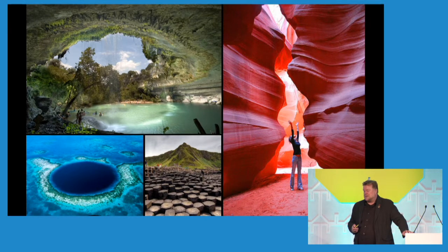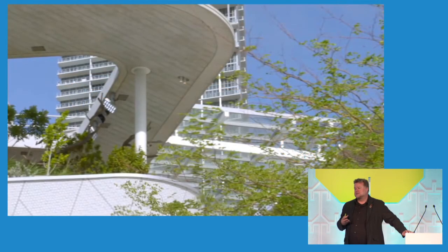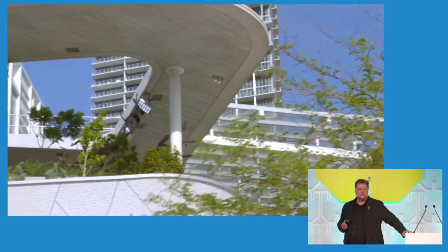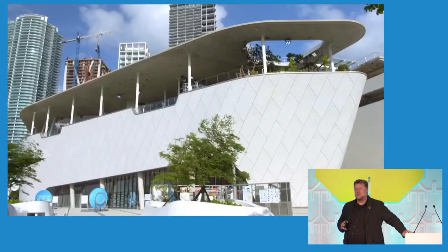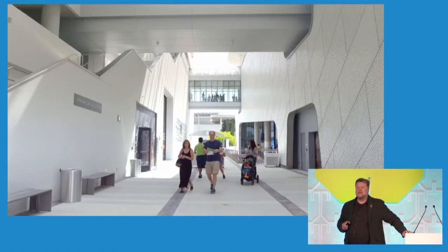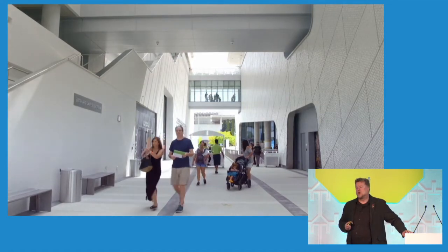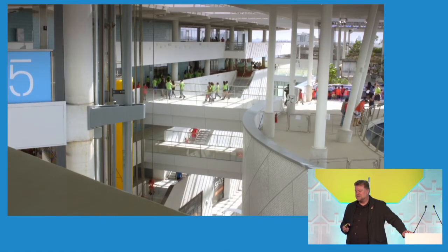And so we came up with the idea of using the cooling winds and breezes that come off the bay and actually rethinking how the building worked so that all of the circulation space was actually outdoors, because most of the year it's actually a very pleasant environment, and if you can cool it with breezes flowing through the building, you can think of it as really as streets. So all of the horizontal and vertical circulation happens in this open street that draws the wind off the bay through it and cools it.